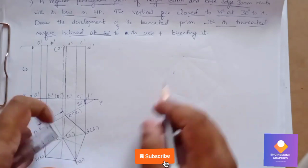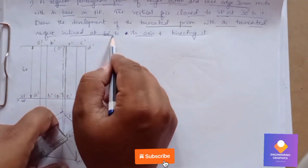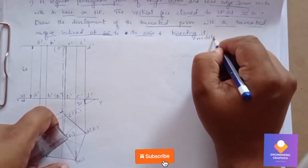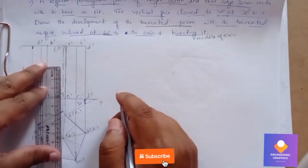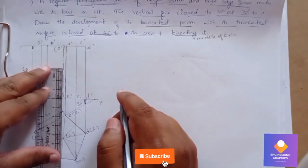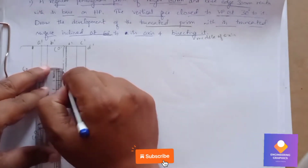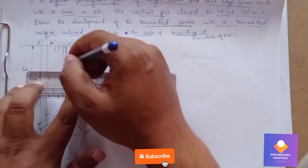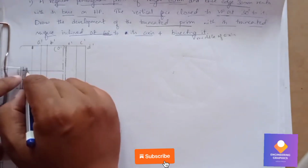Now we have to consider the angle of inclination, 60 degree. Exactly bisecting means exactly half, the middle point of the axis we have to consider. Middle point means if it is 60, we should consider 30 mm. We should consider exactly 30 mm. So you can show the dimension here.